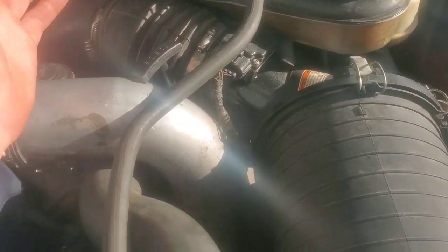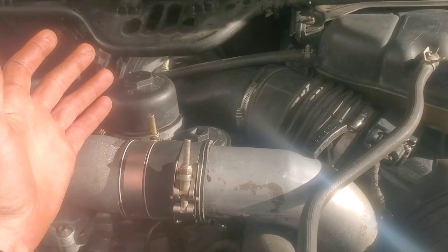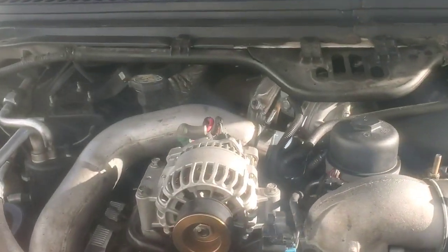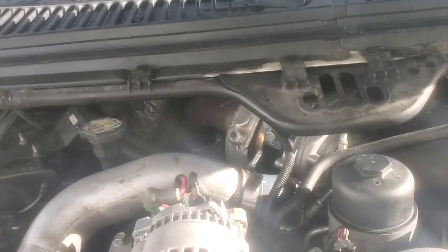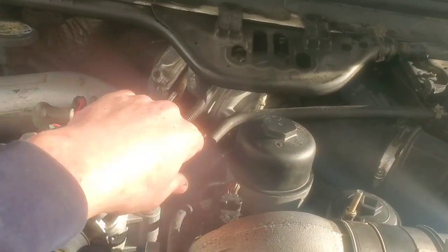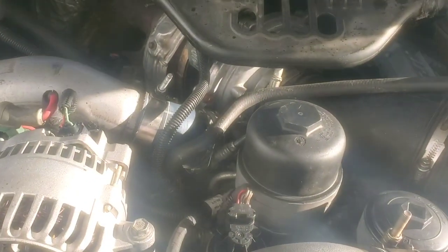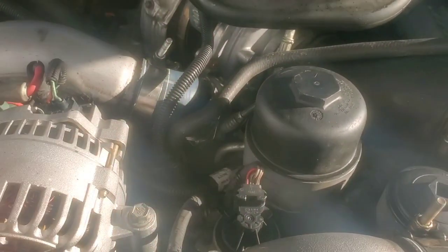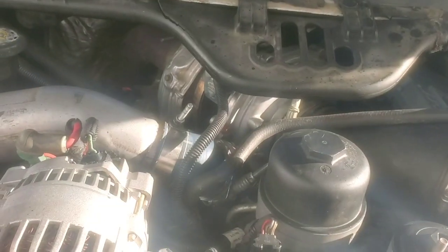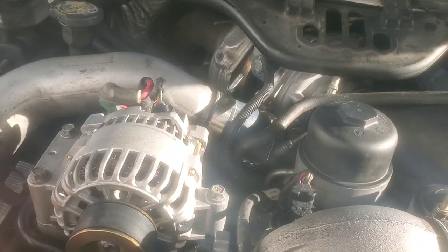We could spend more time with this and try to find the exact spot in the wiring harness, but it's probably just best to replace it anyways, because we're finding all kinds of other spots in this wiring harness. I'd already fixed some, even the very first time this pickup came in. There were wiring issues I fixed down here for the oil pressure switch, or it might have been the oil temp sender, one of those two. I fixed some wires down there when we had this apart and were doing other things to it. At this point, we're just going to get a whole new wiring harness.